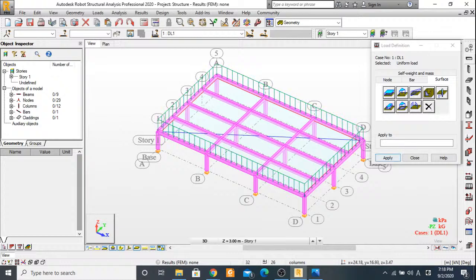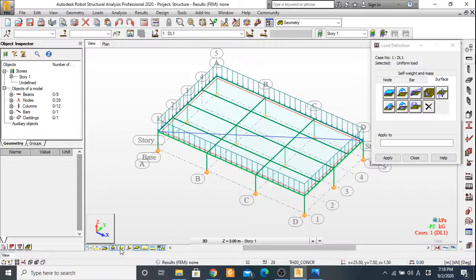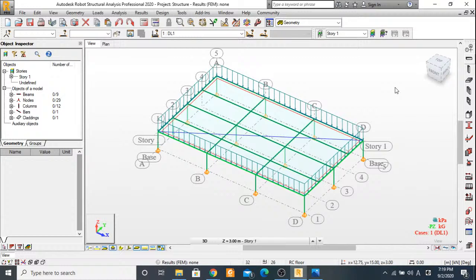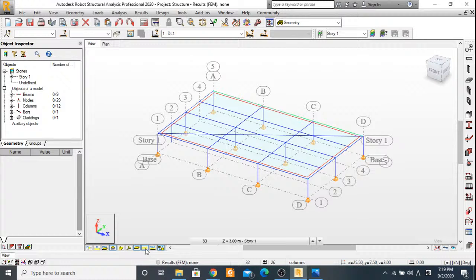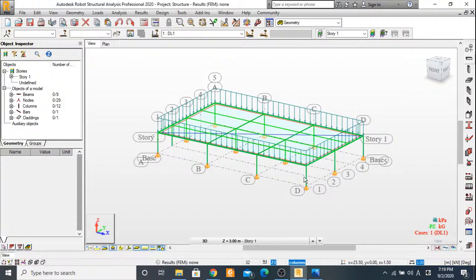And then still on dead load, however, we have an issue, right? So if I go ahead and deactivate the cross section, you will notice something. Let me activate the loading here. Okay, the loading. Let me deactivate the loading and then activate it back. So you'll notice that when I activate, there is some form of green that surrounds all of those members. That green is to show that the self-weight of all of the members have been taken into consideration.